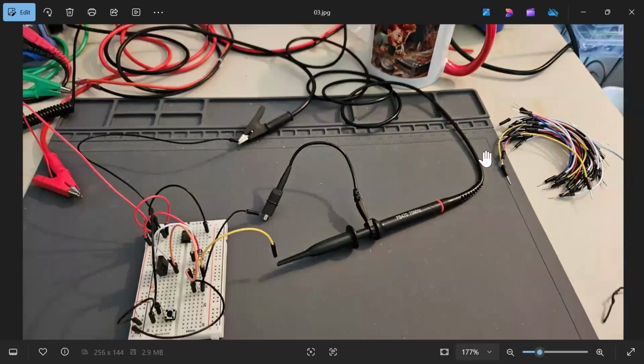Okay, now I've programmed the PIC microcontroller, and that's installed on our breadboard. And now it is hooked up and is controlling the switching of the MOSFET. Now we have essentially a shunt resistor here, and we're hooking that up to the oscilloscope, and we measure the voltage across that shunt resistor. And that gives us a way to indirectly measure the current that's being drawn through the circuit. Okay, so now the PIC is programmed and installed and is controlling the MOSFET. And now we can take a look at that on our oscilloscope.